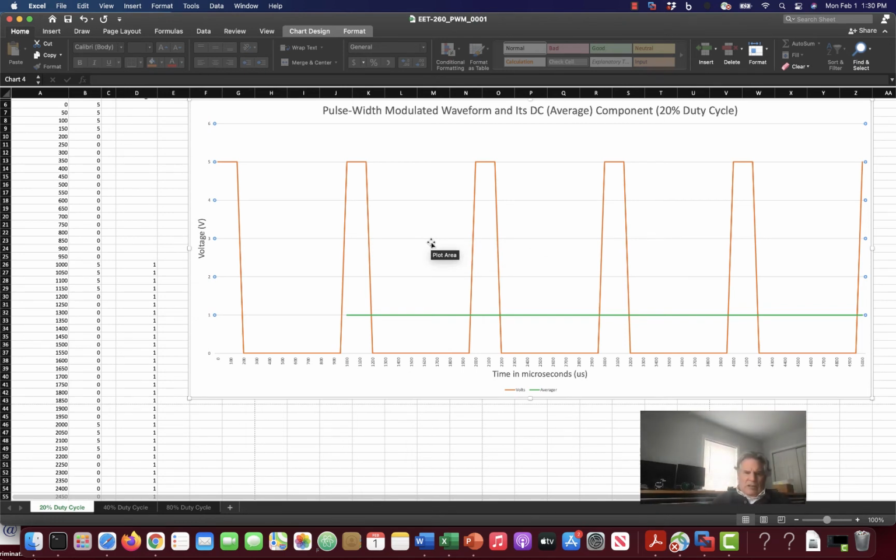And I'm gonna double check myself here because I'm not drawing any diagrams or anything, and I'm talking off the top of my head. But if I take 5 and I square it and I multiply it times 8,000ths of an ohm, well, I did that wrong. I actually came out with 200 milliwatts. So, sorry about that. 200 milliwatts, 0.2 watts while it's conducting. And 1/5 of that would be 40 milliwatts.